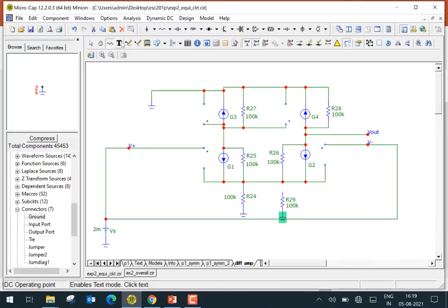All right, and let's connect them up. We have not changed the circuit. The circuit is still the same. All that we did was take the 100K, 50K resistor here and split it into two parts. So now we can see symmetry in a better way. This part of the circuit is the left half, and this is the right half here. They're exactly the same. And as we said, the voltage at this node and this node is the same here.